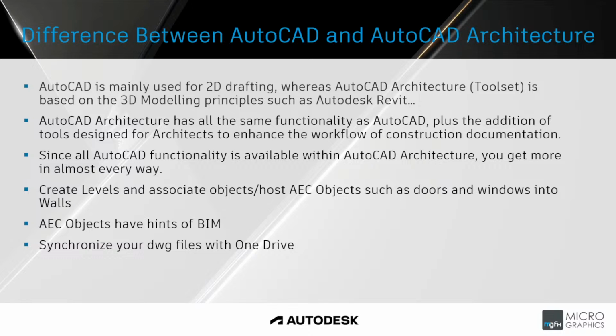It is based on intelligent walls, doors, and windows, which you can find within the ribbon as 3D elements, where you can also select a specific type of wall, single wall, cavity wall, all the above that you generally get within Revit. These are known as AEC objects. These intelligent objects give the designer the ability to manipulate building elements at a higher level, far beyond what dynamic blocks have traditionally offered, concurrently speeding up the process and eliminating possible errors between views.